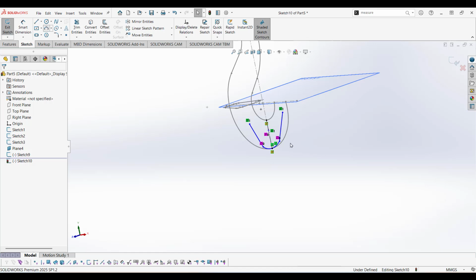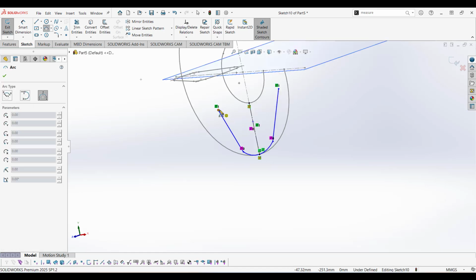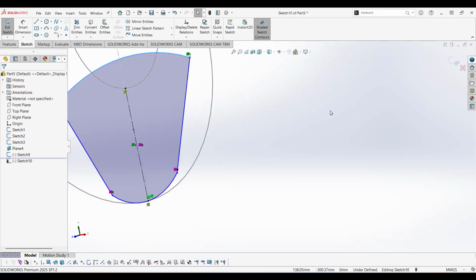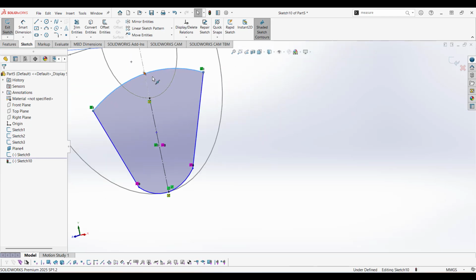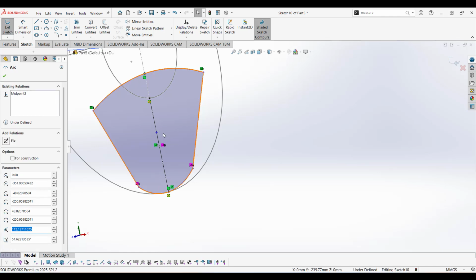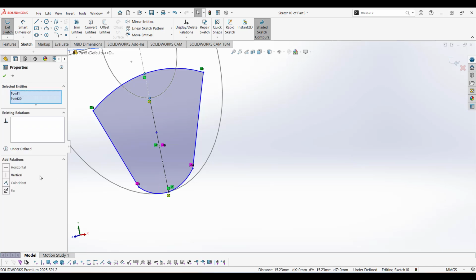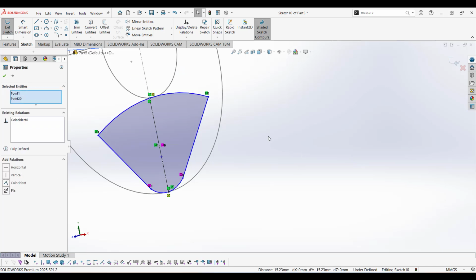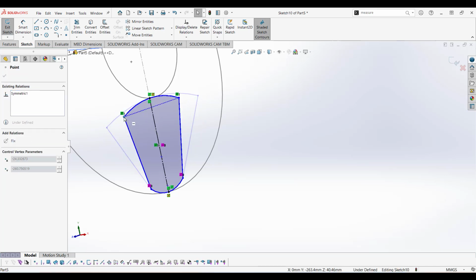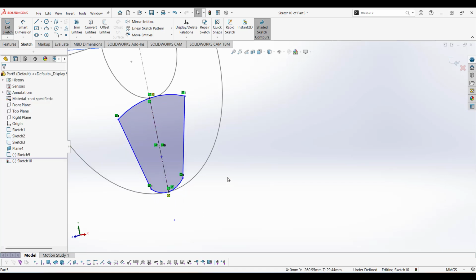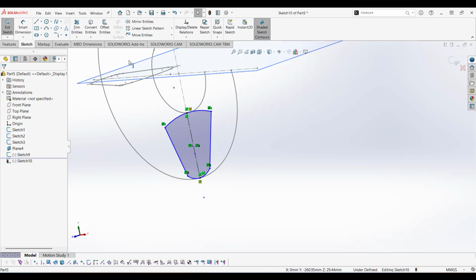Another 3-point curve, start freehand. So now with this freehand, you pick the center line, hold the shift and grab this line and make them coincide. Alright, so let's just make this a bit narrower, and we want to add a fillet of 10 to these corners.